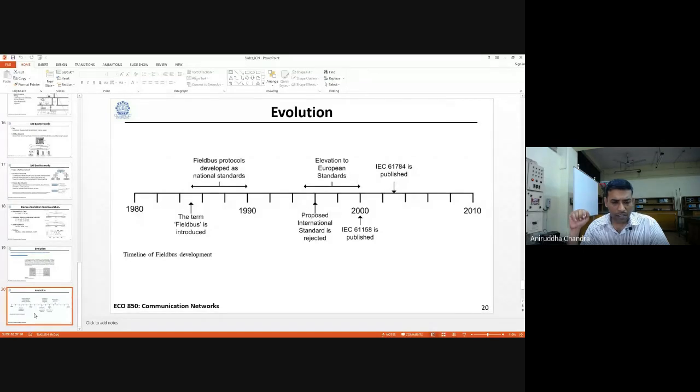And in this control network, we have several layers. The lowest layer is the device layer. On top of that is the I/O layer that takes the information to and fro to a controller. The controller is the PLCs, which form layer 3. On top of that, we have a human-machine interface layer, and on top of that, we have a management or planning or record-keeping kind of layer.